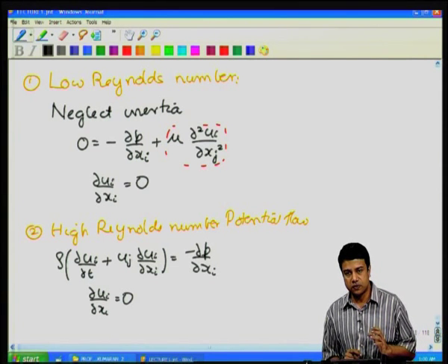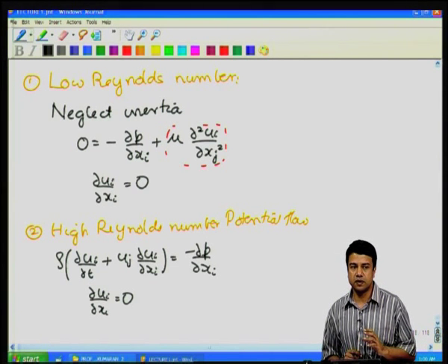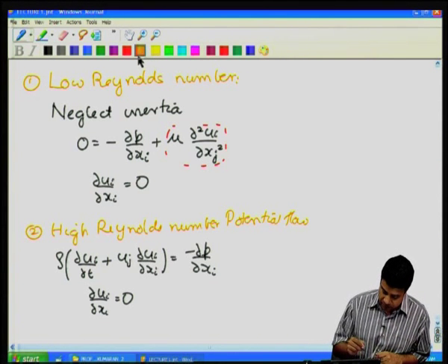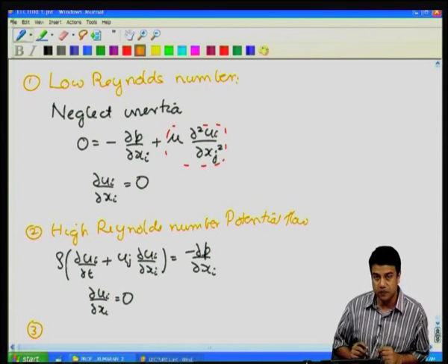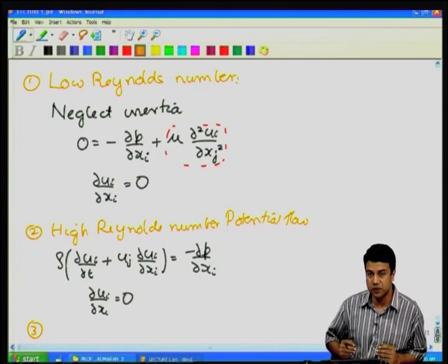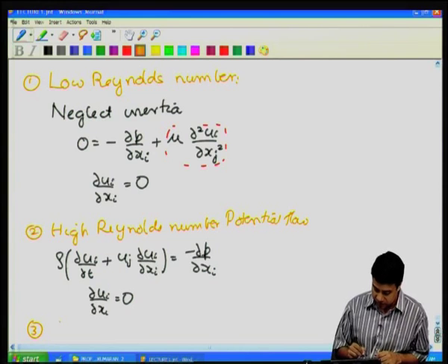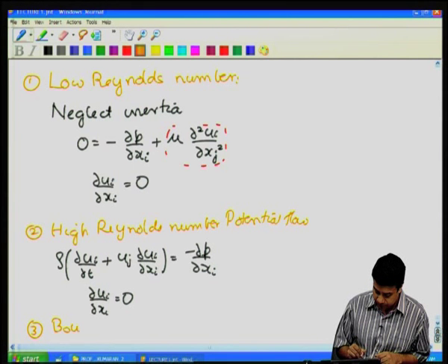In this case, one can no longer satisfy the tangential velocity boundary conditions for the velocity or the stress, because I have neglected the highest derivative. And then the third step will be to include that very near boundaries, because I realize that transport to boundaries has to take place only due to diffusion, and that is boundary layer theory.